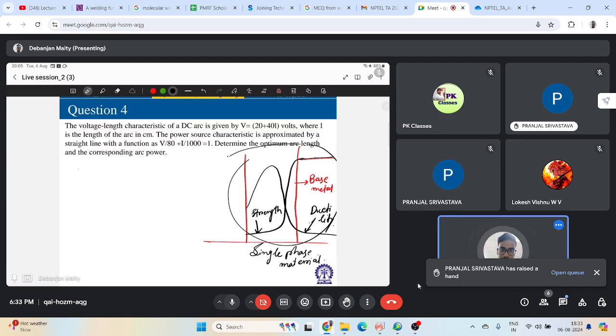There will be something called precipitation formation. So I will call it a different hardening mechanism. We call it precipitation hardening or age hardening, which will govern the strength of the joint if you are doing some dissimilar metal joint, right?